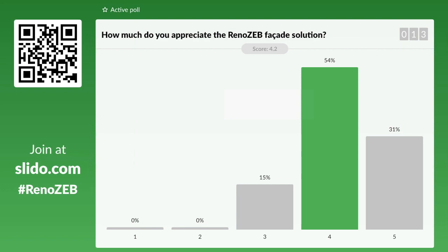When I speak about the performance test, it's not thermal performance. Thermal performance is validated in CUBIC, and it's an ongoing activity. When I speak about performance test, I speak about the EN 13830 norm. That is the standardized norm for curtain wall facades. And in particular, we speak about air tightness, water tightness, impact resistance, and wind load resistance. This is the performance for curtain wall facades.